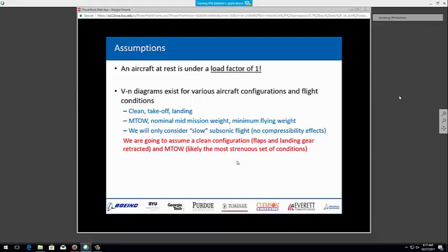The design maneuvering speeds are the intersection of the maximum load line and the stall line here. You have a design maneuvering speed on the plus side, and also a design maneuvering speed on the negative side. Military aircraft in a dogfight will be up in this area here, near stall, because they're pulling a lot of lift coefficient in high G turns, and so that puts them up in this part of the envelope where they're near stall when they're breaking the airplane.